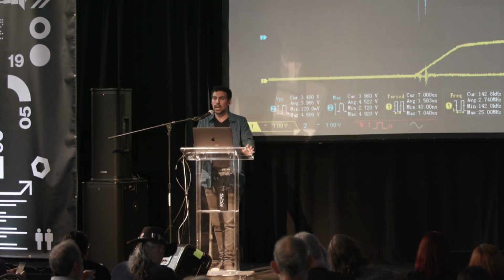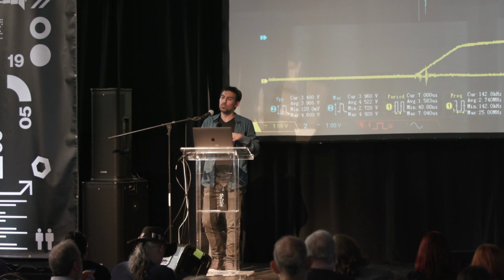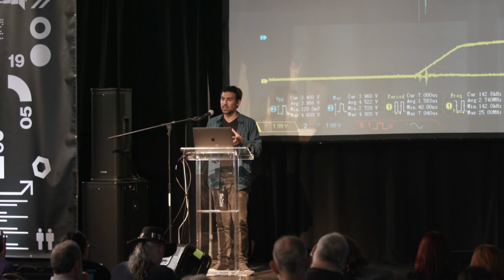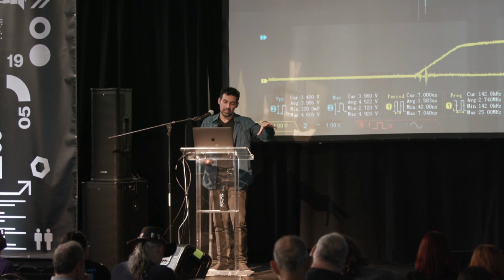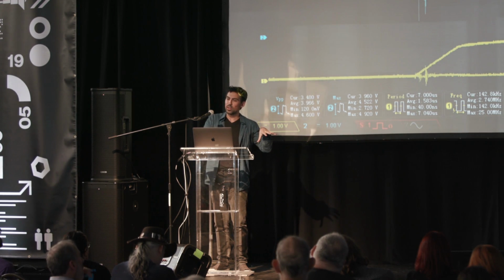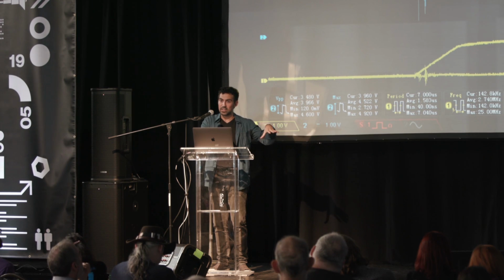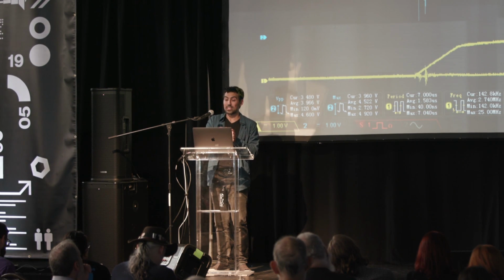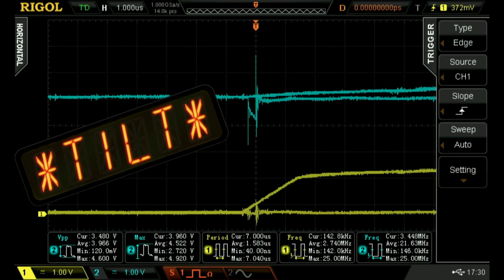And traditionally in these attacks, at least in voltage glitching attacks, you want to remove any bypass capacitors to prevent decoupling. So normally you have a voltage regulator, and that's applying your power to your chip. And then we have some bypass capacitors. So if the regulator can't provide enough power for some peak moment, those bypass capacitors will help you. But this is essentially a tilt, right?